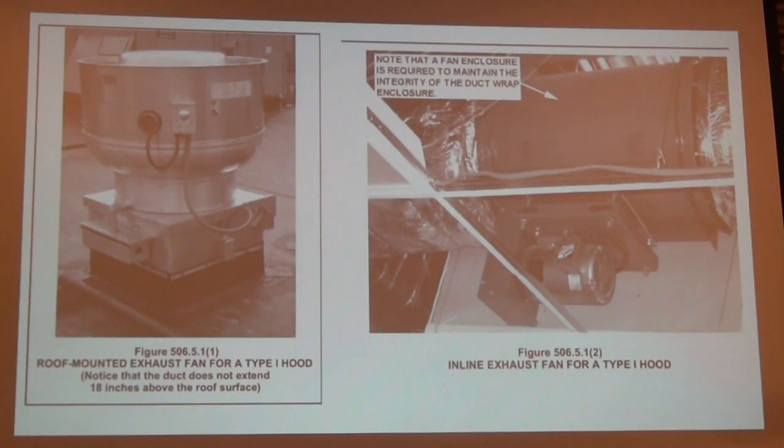Then you have the inline fan. With this inline fan, if it's required to have a duct wrap, the fan itself is supposed to be wrapped, which is almost impossible to do around the motor. So I tell them to do the best they can, and they wrap them.